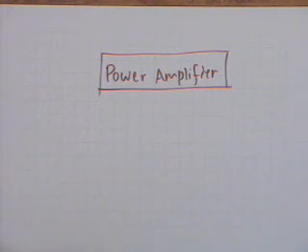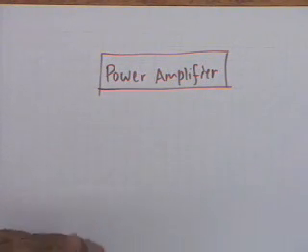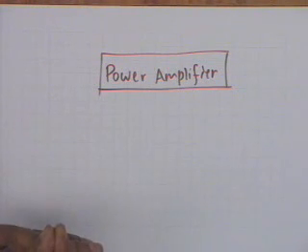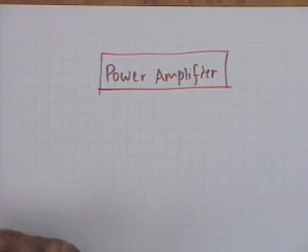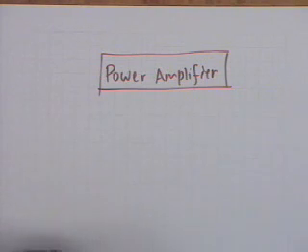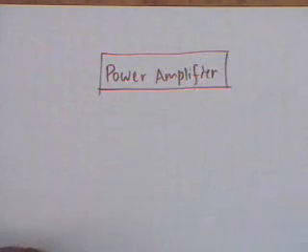Well, the difference between power amplifier and other amplifiers is that in a power amplifier your aim is to get as much power as possible into the load, and the ideal situation would be that whatever power is drawn from the battery, VCC multiplied by I sub C, that is the power drawn from the battery? Not quite. A little bit of power is also drawn at the base, isn't that right? VBB multiplied by I sub B.